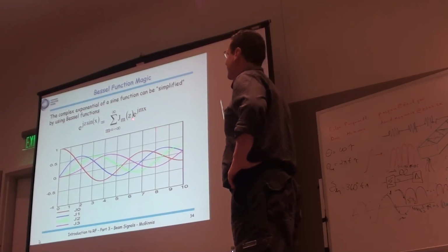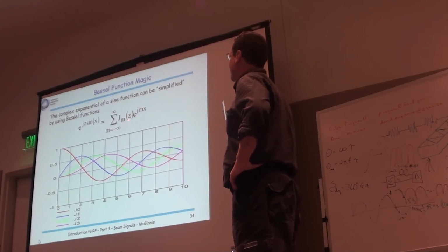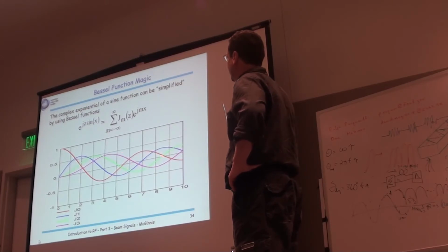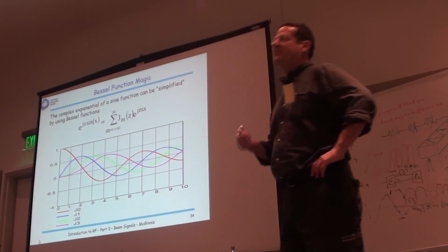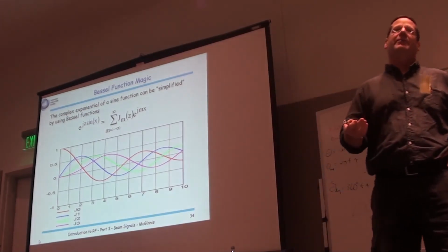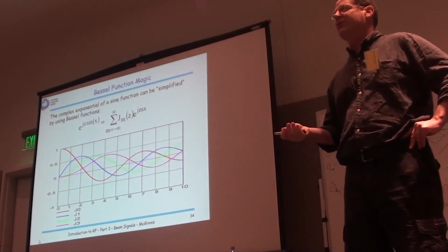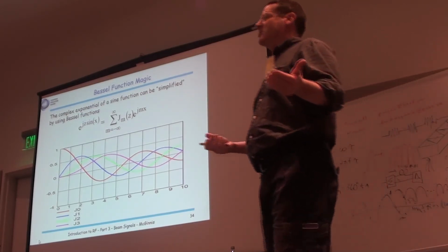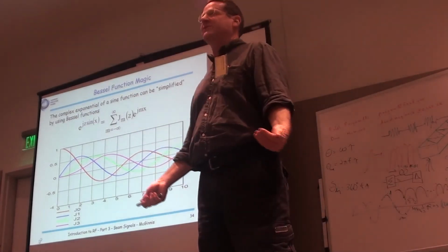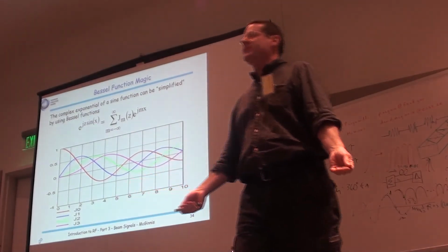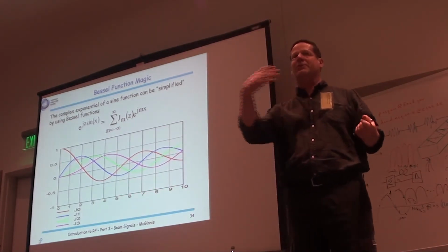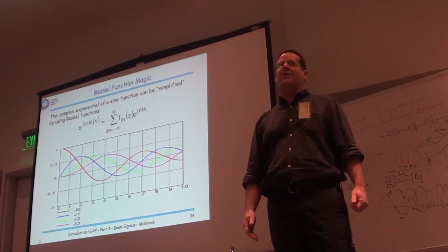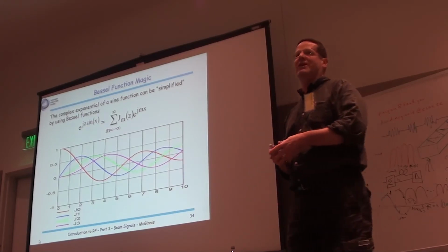So now I can actually look at that in terms of the spectrum analyzer. But now I'm going to have an amplitude here, which is given by the Bessel functions. Here's J0, here's J1, here's J2, here's J3. People get freaked out about Bessel functions. Don't get freaked out about Bessel functions. They're just like sines and cosines. You just know sines and cosines from fourth grade, but if we had lived in the cylindrical world, you would always know how to do Bessel functions instead of sines and cosines. So there's no reason. You go to a book, you go to a computer, and they're just the same thing as a sine or a cosine. They just have an extra index on them.